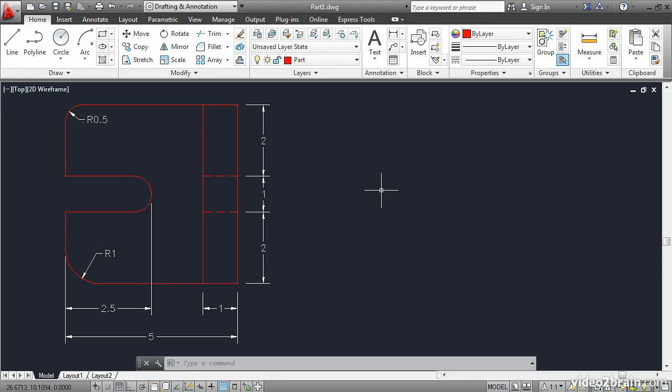In this lesson, we will explore grid and snap. The closest analogy to grid in the real world is graph paper. Snap, on the other hand, essentially quantizes space so that your cursor no longer moves continuously, but instead snaps from one place to another, according to a spacing value that you set.